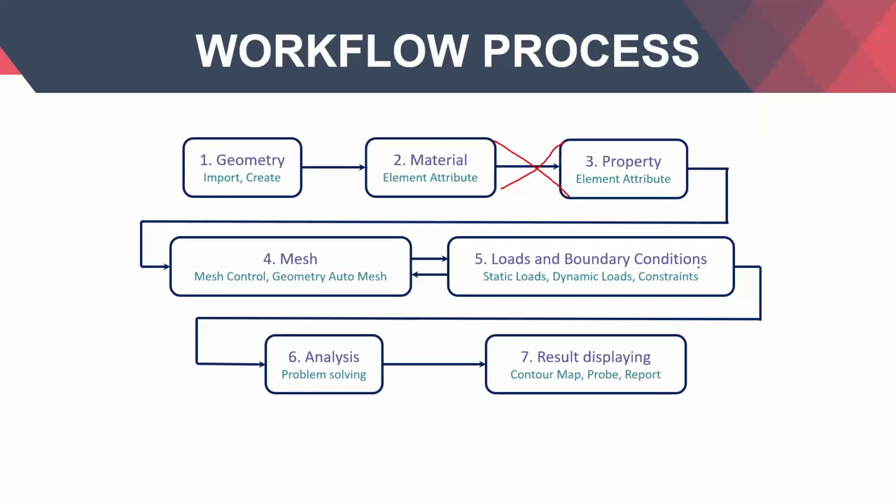So in the geotechnical modeling, we normally go for roller supports on the sides and fixed supports on the bottom, but obviously that is not exactly valid for structural elements. So it depends on what kind of ground boundary conditions you want to provide to your model. Finally, after that, you come to the analysis creation part, and then the software or the solver solves the analysis for you. Then the results, where you get the contour maps, the probes, and the reports. So the first part of the PPT is over. Now we'll go to the numerical model description.